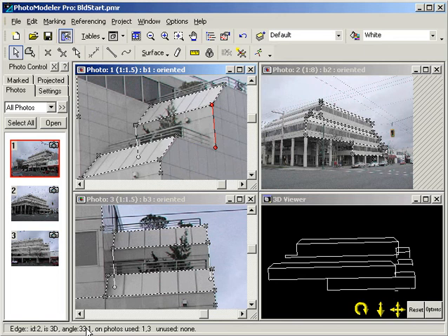If the angle between edges falls below 20 degrees, the accuracy of the edge will drop. Similar to most referenced 3D objects in PhotoModeler, the closer the angle is to 90 degrees for the photos, the better the result will be.